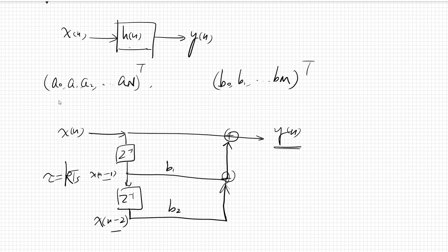Well, in this case, when you receive it, because you sample exactly at the symbol period, you neglect whatever is in between 2 symbols. But in reality, maybe you need to do oversampling. So you can capture all these delayed versions in a denser time period, denser than T sub s.